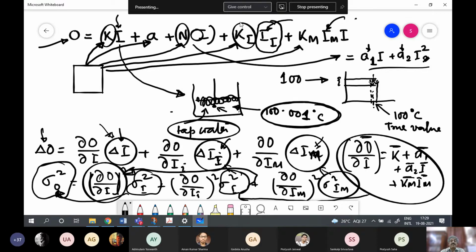What I'm saying is that when you are trying to understand, the data sheet tells you what is the sensitivity when you are producing, let us say, 100 temperature sensors or 100 strain gauges of nominal resistance 100 ohms. Then of course in a batch, when you buy a particular piece, it may be 100.01 ohms or 100.1 ohms. It may be.